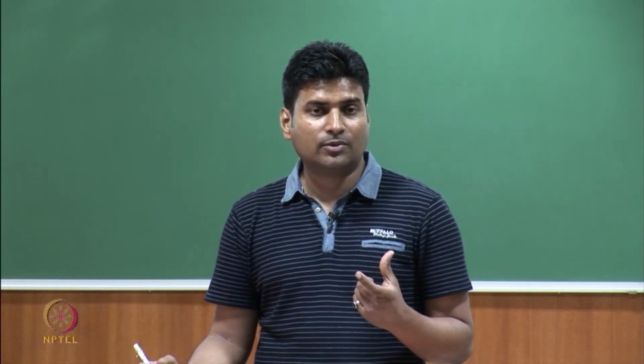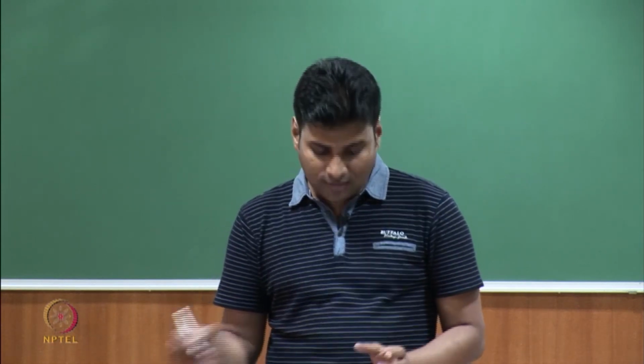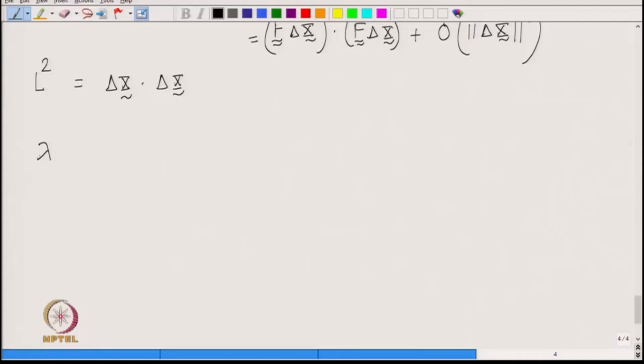If we denote the stretch by lambda, then what is lambda square? So, lambda denotes the stretch. So, lambda square is then simply the final length square divided by original length square, right. So, that is the square of the stretch. It is not the strain, it is the stretch. So, stretch is simply final length divided by original length.